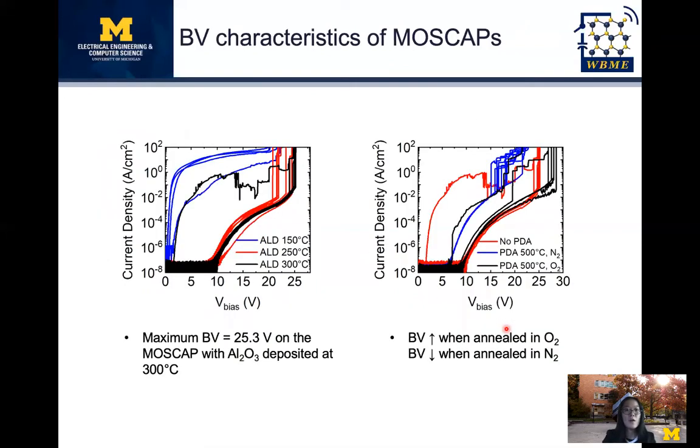We also characterize the forward breakdown of the MOSCAPs. Here we can see when we increase the deposition temperature of ALD, the breakdown voltage also increases.